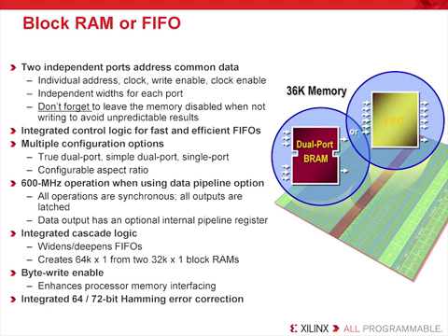Virtex 6 block memory also includes a pipelined register option, which improves the speed to up to 600 MHz. This architecture includes output registers that provide a faster clock rate, but the caveat being that it provides increased latency. Block RAMs are also cascadable, which means they can be connected together to make larger memories or FIFOs. Virtex 6 also has a byte-write enable functionality that is helpful to embedded designers that are targeting embedded applications using the MicroBlaze soft processor core.